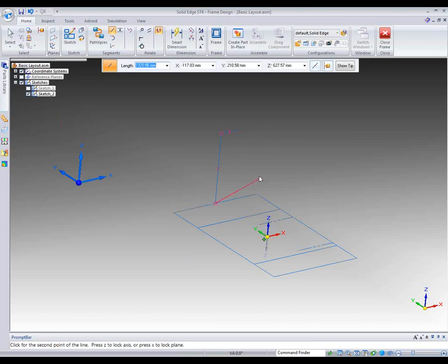All right, I'm going to start from here. And we want to pick up an end point here. And straight up in the Z, and this one's going to be 750. Once I've got this basic information in here, I want to be on the plane here, this ZX plane. So if I press the X key, I step around the plane. So there we go. Again, come out here, the Z and the X at least, 300.